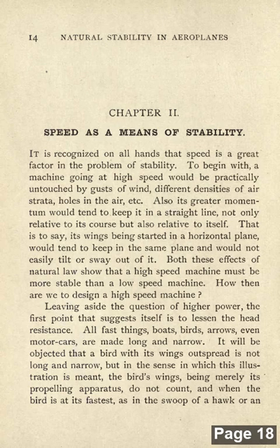How then are we to design a high-speed machine? Leaving aside questions of higher power, the first point that suggests itself is to lessen the head resistance. All fast things, boats, birds, arrows, even motor cars, are made long and narrow. It will be objected that a bird with its wings outspread is not long and narrow. But in the sense in which this illustration is meant, the bird's wings, being merely its propelling apparatus, do not count,